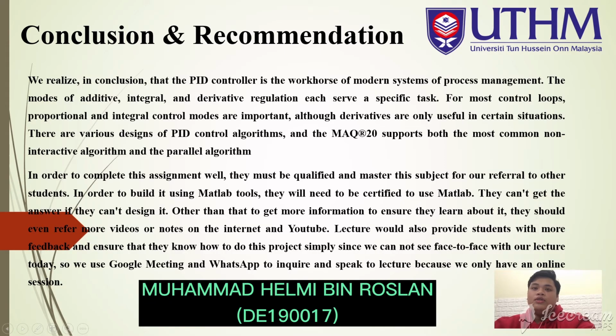Conclusion and recommendation. In conclusion, the PID controller is the workhorse of modern process management systems. The modes of proportional, integral and derivative regulation each serve a specific task. For most control loops, proportional and integral control modes are important, although the derivative is only useful in certain situations. There are various designs of PID control algorithm, and the MATLAB supports both the most common non-interactive algorithm and the parallel algorithm.